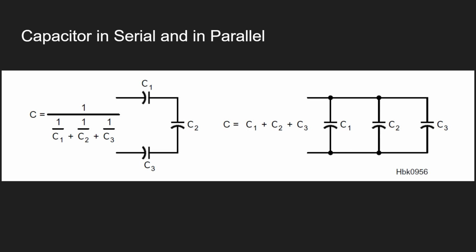Do you understand what the question is? It's because if you connect the capacitors in this way, they can withstand a higher voltage. That's why sometimes you may sacrifice the capacitance, but the overall circuit can withstand a higher voltage.